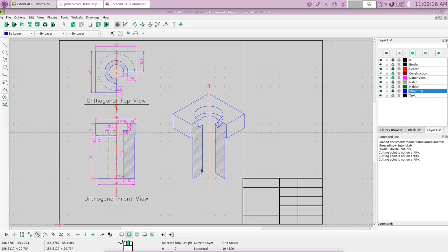Now we have to cut this bottom circle, because a portion of this is hidden. So if you choose divide and choose snap on entity, and it says here specify the entity, that would be this one, and then snap on that entity, click, and do the same on the other side here, and you will have left these bits of line in here that you cannot really see from this view.